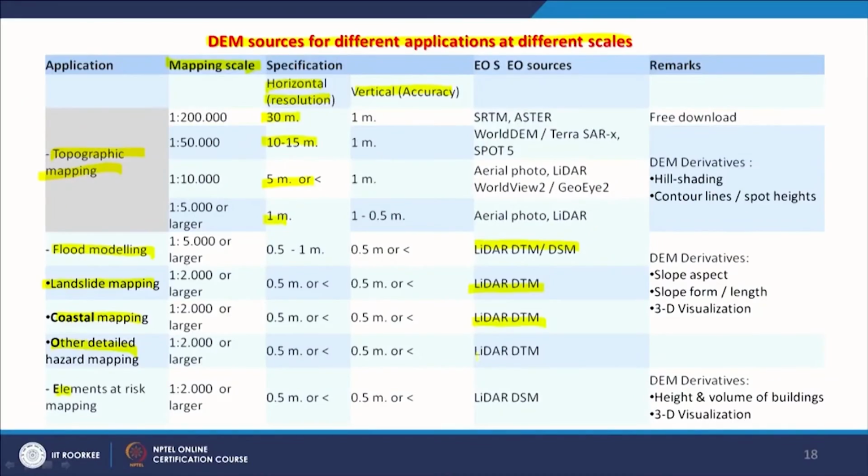So one has to be really careful while bringing up these issues. The rest of the techniques are based on different methods, such as ground based radar, and like SRTM, the ASTER DEM. ASTER is again stereo data based, created for the entire world and available free of cost at 30 meter resolution. SPOT you can generate on your own, but this ASTER GDEM, the global DEM, is available free of cost, and of course Cartosat is also available at 30 meter resolution.